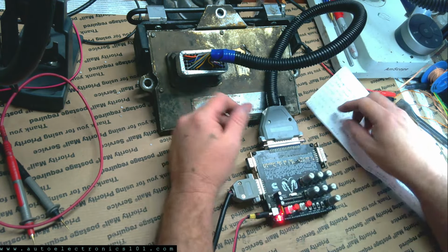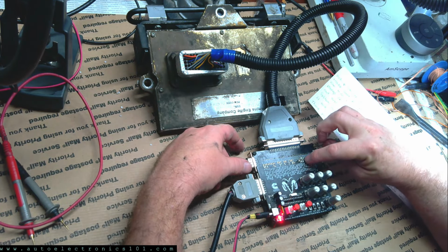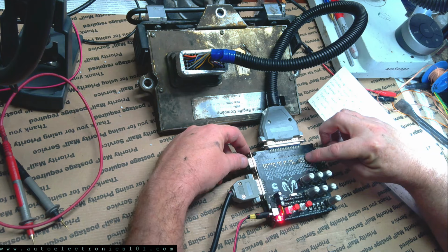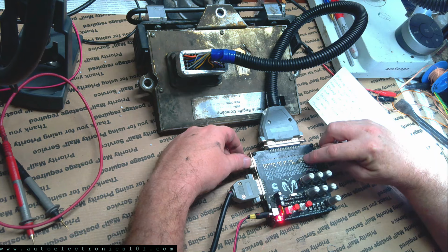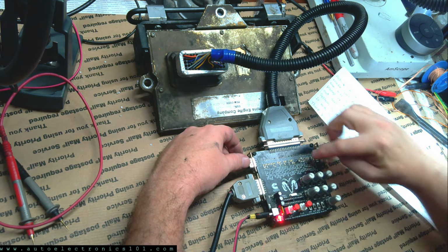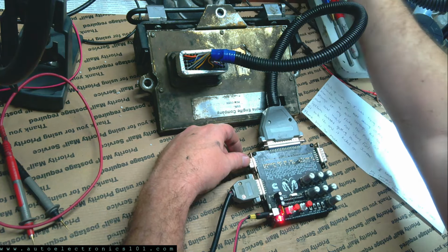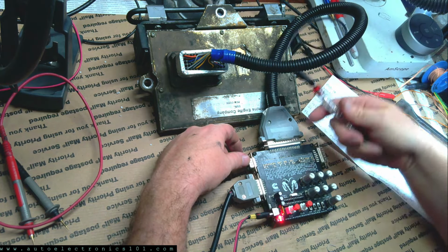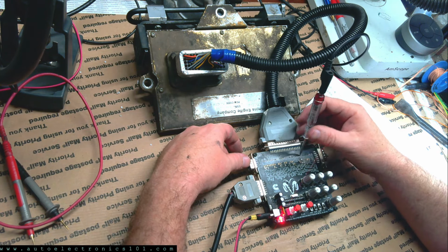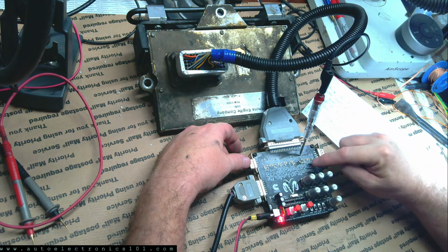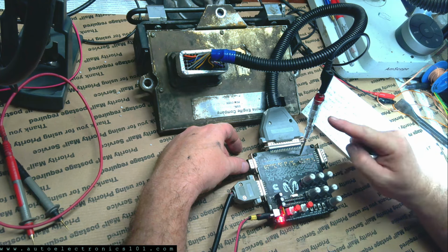Okay. So now what we should see here is our white wait to start light come on. We should see our fuel pump relay LED come on. But I think something's wrong with that LED. I think I messed it up on a different job. So actually, I'm going to put this lamp here, this test light, until I can fix it. I don't feel like fixing it right now, but I'm going to put that lamp there, and that is for the relay control for the injection pump.